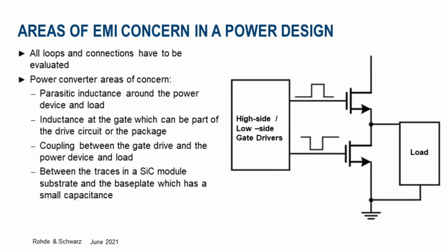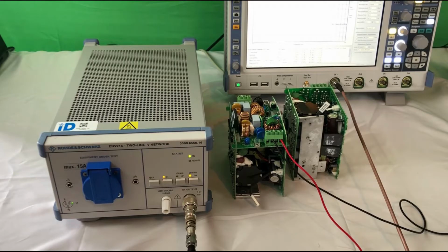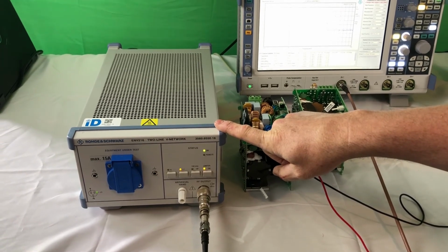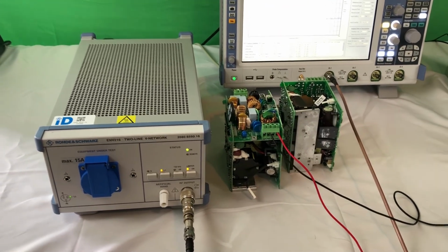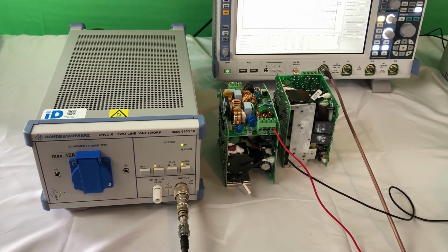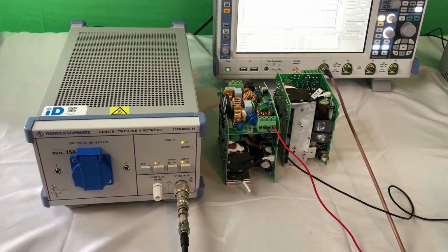In the past, oscilloscopes were not commonly associated with EMI testing due to performance, FFT, and analysis limitations. However, that changed in 2010 when Rohde & Schwarz introduced the RTO oscilloscope series with a number of innovative features and enhancements. Along with the scope, EMI pre-compliance testing requires a line impedance stabilization network, or LISN, which acts as a low-pass filter, preventing high-frequency noise from coupling into the system from the source.